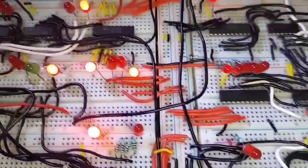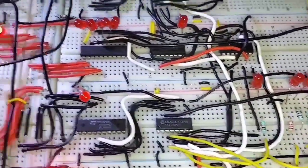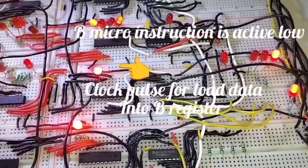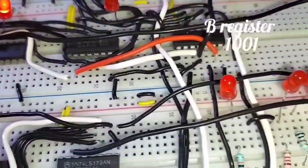Now we are at the final step, that is step 3. We have completed the 3 steps from 0 to 2. Final step is 0111. When we give the clock pulse in this step, the data of the RAM which is on the bus will be fed into the B register.